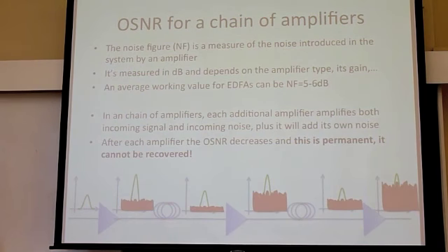So before, we've seen the amplification, but then what happens when the signal goes through the fiber? Both the noise and the actual signal get attenuated, some of it gets absorbed, and the light associated with them basically gets lost, so both powers are reduced. It's a bit different from electrical, because in electrical you have electrons which still move depending on the temperature. But in the fiber, that doesn't happen. So the fiber doesn't actually generate photons which are noise.